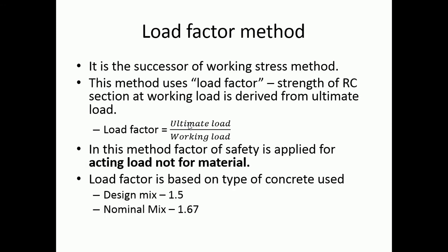Okay, next is load factor method. This method evolved after the working stress method, so it is a successor of working stress method. This method uses a load factor. Load factor means the strength of the section at working load is derived from ultimate load. So here we will not be touching the strength of the material. Instead, what we are doing is enhancing the load, applying some load factor to the working load, and converting that working load into ultimate load.